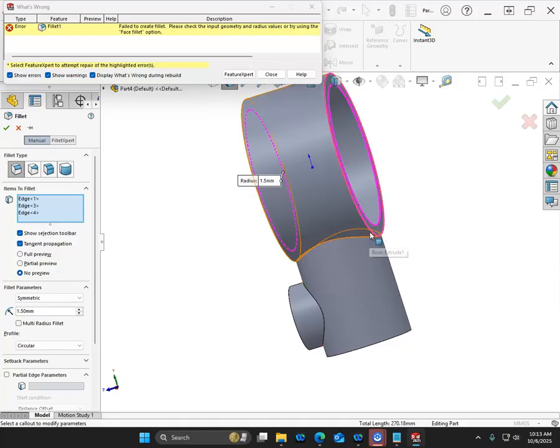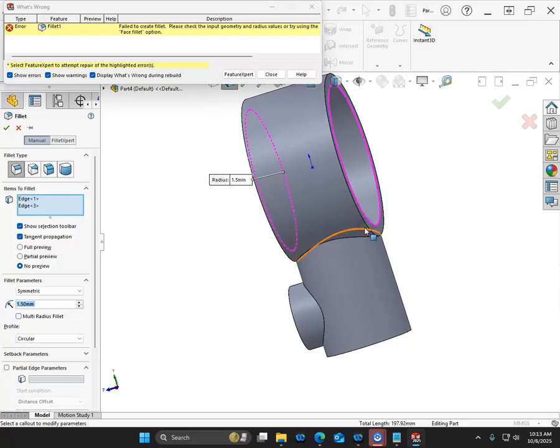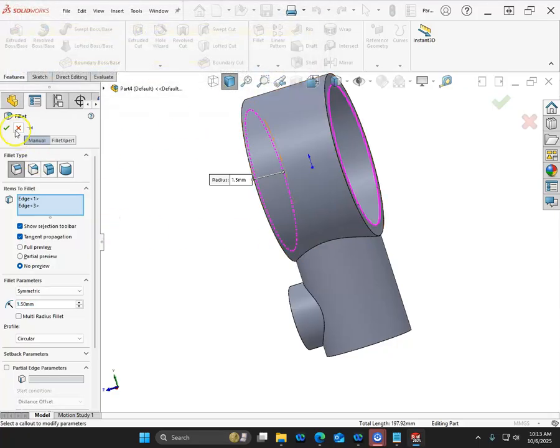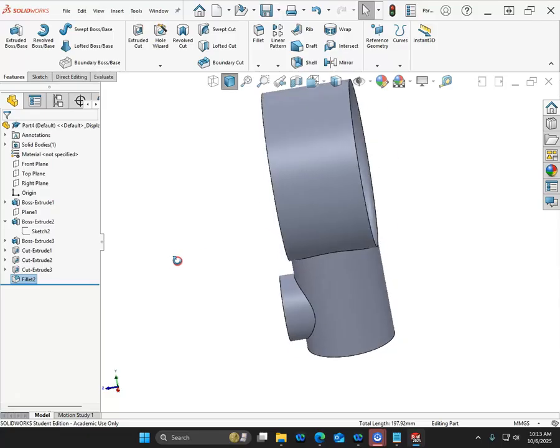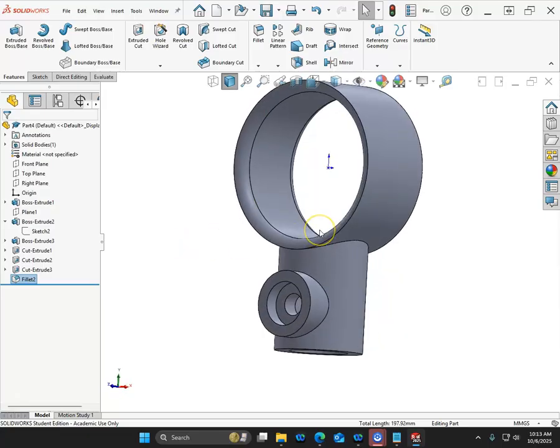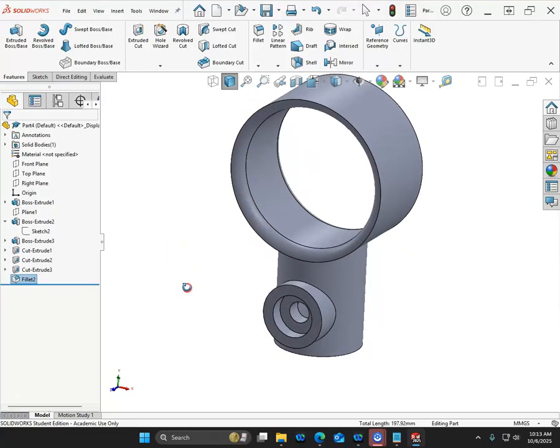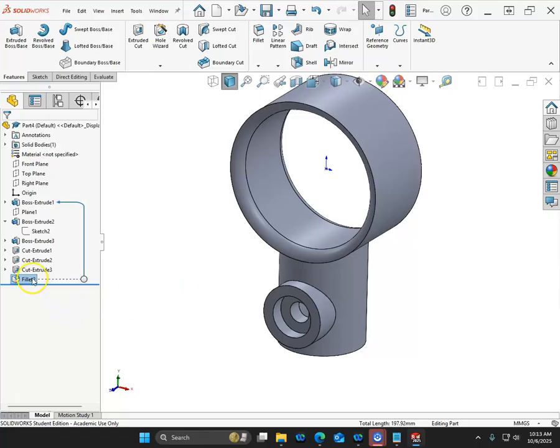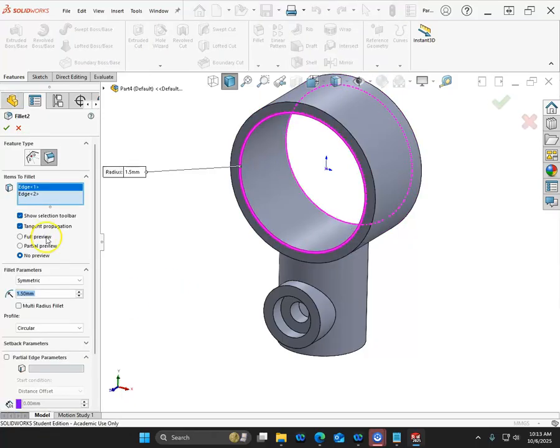All right, this is where it gets a little strange, is the bottom one is going to have a little bit more of a blend issue. So let's go ahead and close that and try again. So the inside, oh, you know what? It's not 1.5 millimeters. It is 0.75 because we had 23 minus 20 was 3 millimeters, 1.5 for the thickness, and then we need to go 0.75.